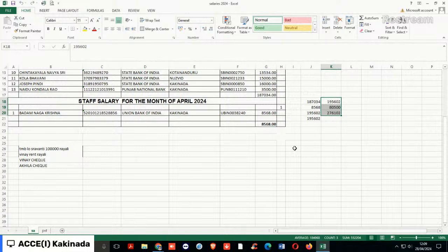Why is this diagonal tension developing? It is the closing moment or the opening moment acting on the beam. In the case of seismic loading, it will be in either the clockwise or the counterclockwise direction due to closing or opening moment generation in the beam-column joints. That is responsible for this joint rotation, in addition to the beam and column rotations of the structural elements. That leads to the development of diagonal tension cracking in your beams and columns also.